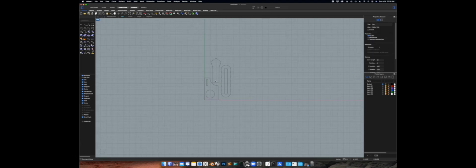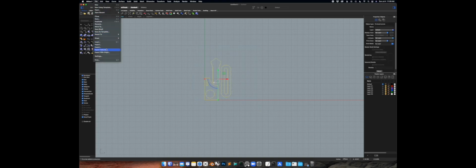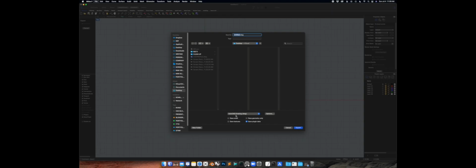So now we're ready to export this file and send it off to the contractor doing the routing, or the department doing the routing. So I would select these items, go to Export Selected, and I would choose AutoCAD DWG. You can go into the options and choose Export Scheme. I always use 2007 polylines, and that has always worked for me.